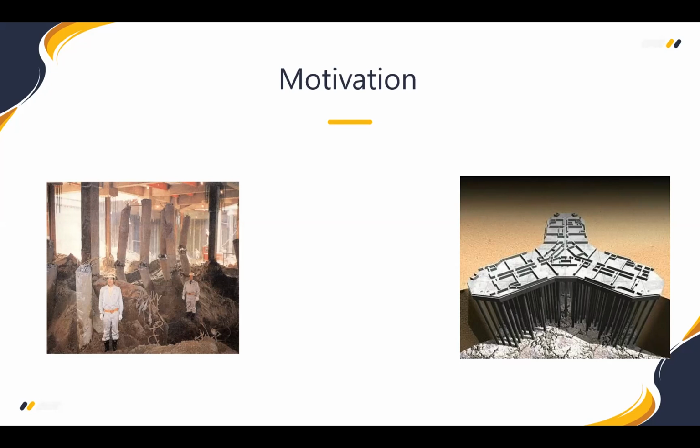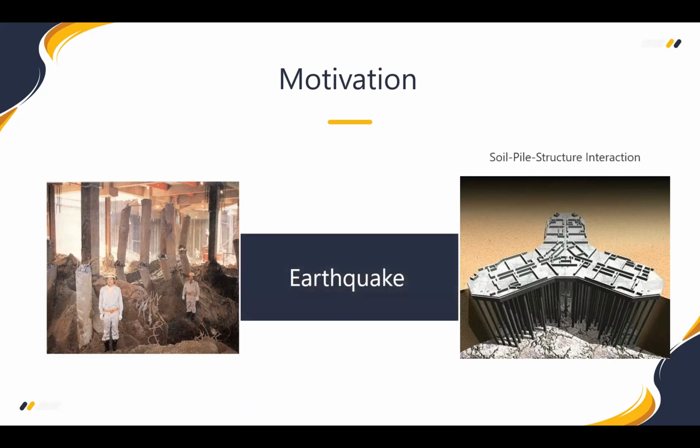According to the municipality of Dubai, every building in Dubai is built to withstand earthquake impact, and the Burj Khalifa itself is built to withstand an earthquake of magnitude 7. We chose to focus mainly on soil-pile-structure interaction because, through hearing our professor's lecture and doing some research by ourselves, we found that soil-pile-structure interaction has an impact on the fundamental natural period of a building.